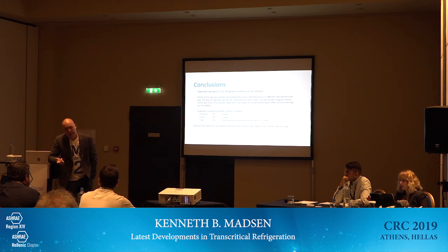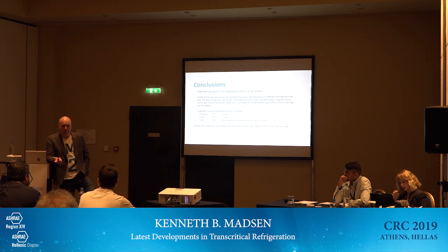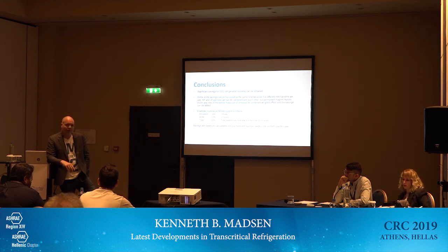That means that quite often we see these low-charge ammonia systems where you have a brine circuit on the low side and sometimes also some kind of air-cooled or water-cooled condenser. We quite often see it on heat pumps right now in Nordic countries, where this is a COP application where you are measured very hard on COP.